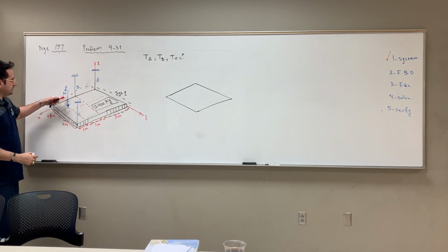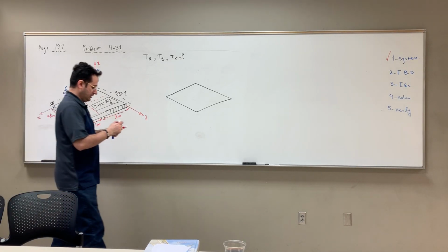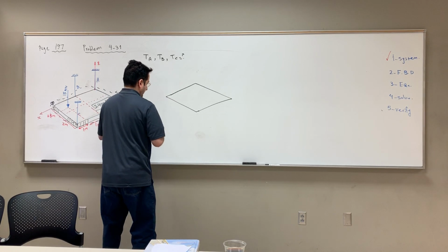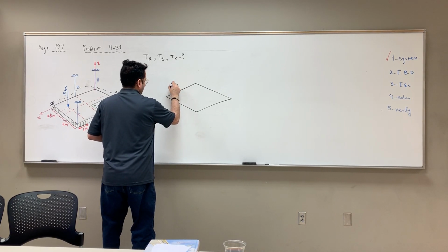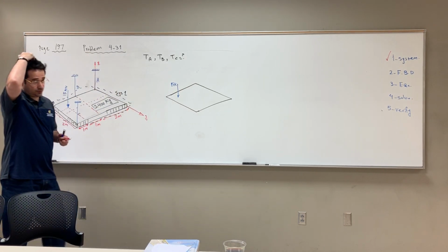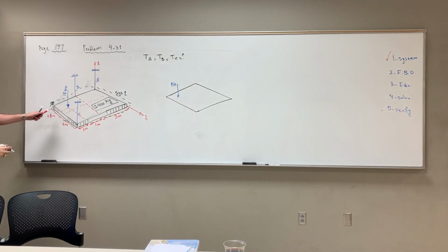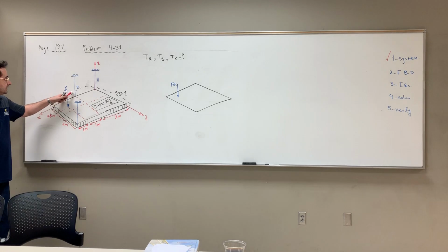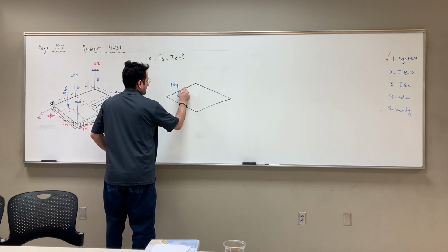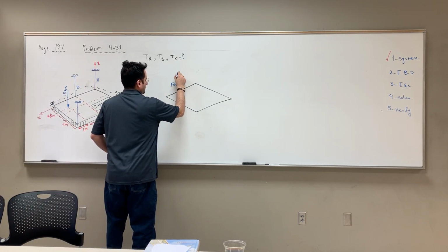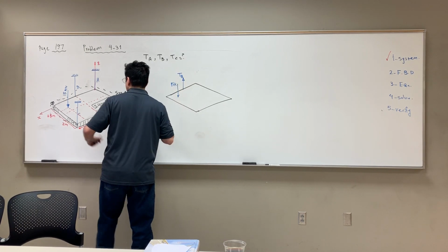The first thing I caught here is the 15K force. Do I have it? Yes. So I just put 15K. If I don't have it, I introduce a variable unknown. Now continue walking. The second thing you caught from the surrounding is the cable, right? So the tension in cable, do I have it? No. So let's call it TD, unknown. Introduce a variable.